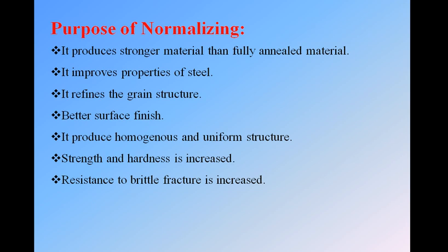Cooling rate is higher, hardness will be higher. So these both are directly proportional to each other. Next, to improve properties of steel means you can increase its strength, its toughness, its somewhat ductility. So it improves some mechanical properties of the material.